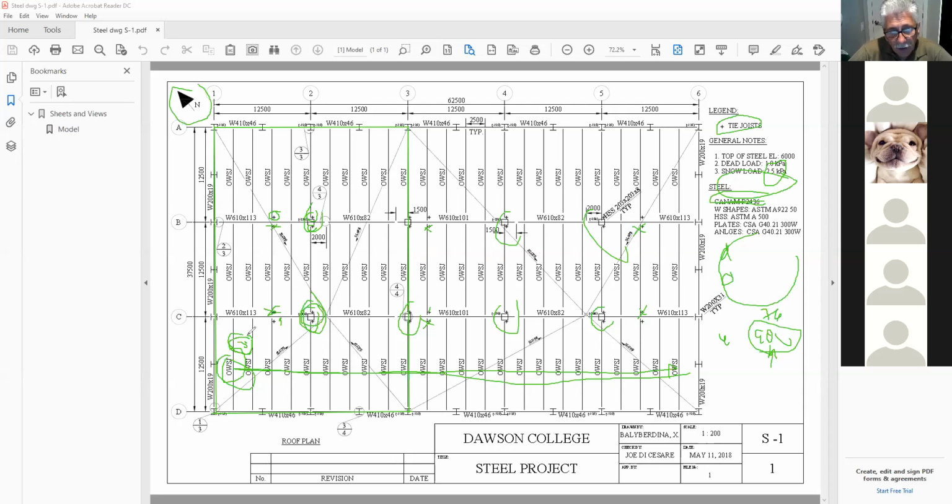Whatever size plate you determined for your HSS connection is the same thing as the plate you're going to be using as your gusset plate. Okay, so if I used 6 millimeters for the other plate, I could use 6 for the gusset plate? Yeah, because if 6 was good for the plate for your HSS, that means all the bearing and everything else is good. Then it's going to be good for your gusset plate. The only thing you have to check for the gusset plate is to make sure that it doesn't shear out. Understand?